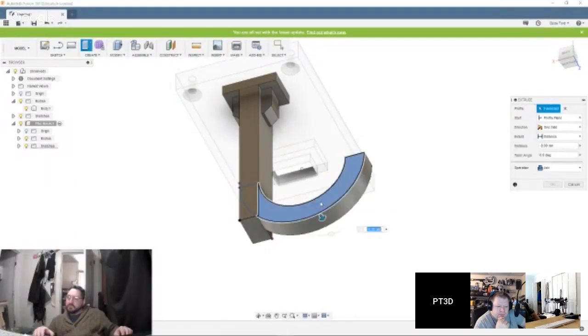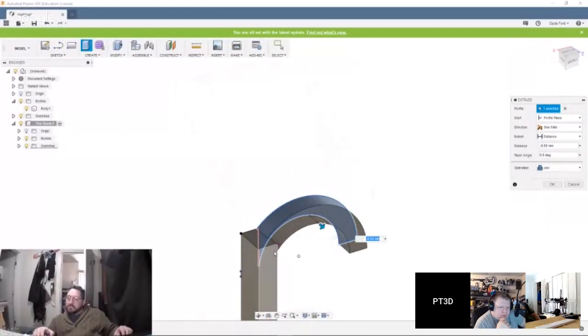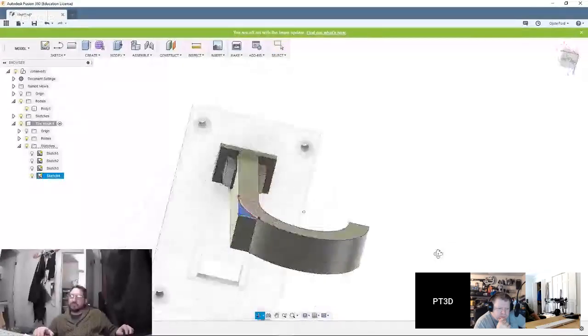All right. Click that. Go down. It doesn't matter now. Go down and hit the bottom face of the main board. Oh, that one? Yep. Ah, there we go. Auto extrude to it. Cool. That's kind of new. You used to have to go in and actually tell it you want to do that. Now, since the newest one, if you click on that face, it'll just assume you want to extrude to it. You can do the same thing, flip it over and click on the other side, and it'll automatically cut it.